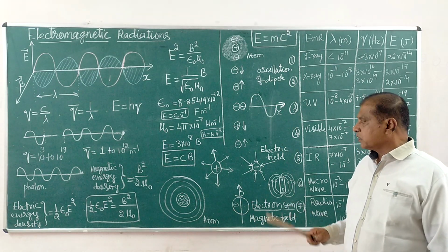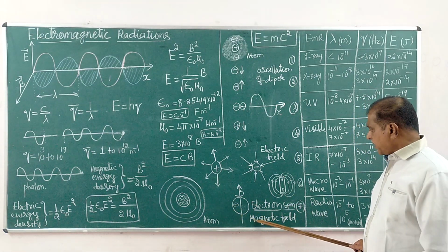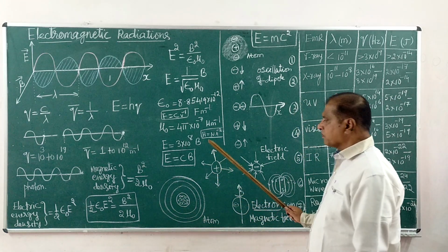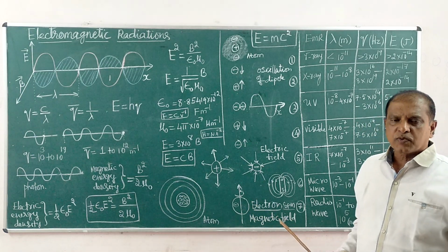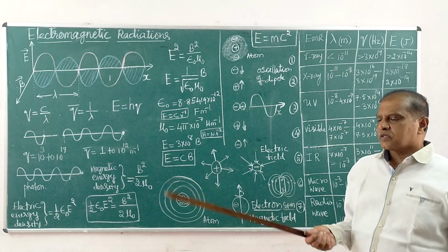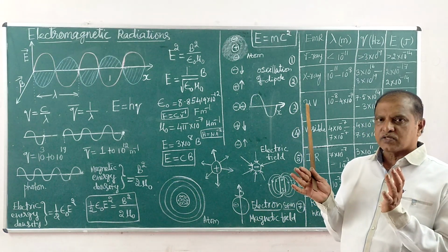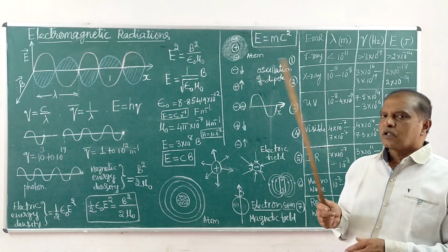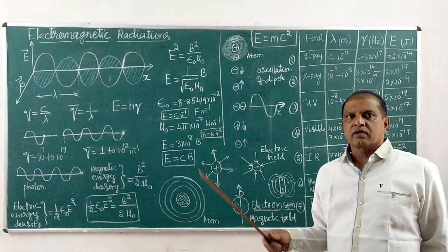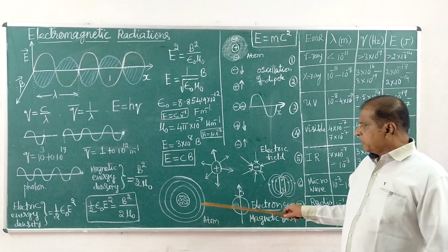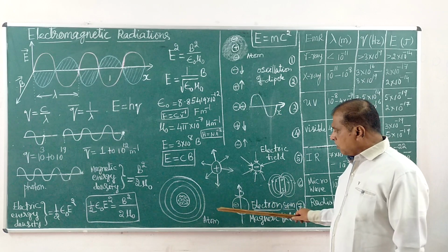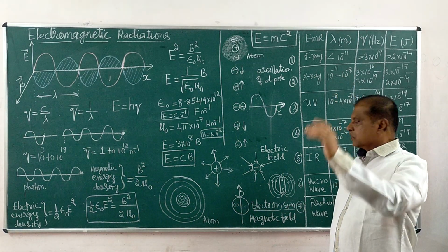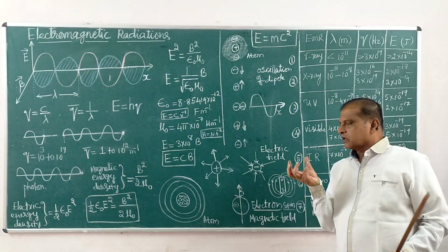But it is possible to have a magnetic field by processing of the material. What is processing? By having a proper crystalline structure, and by using heat treatment or electric treatment, it is possible to make all the unpaired electrons have one orientation, spinning in one direction.